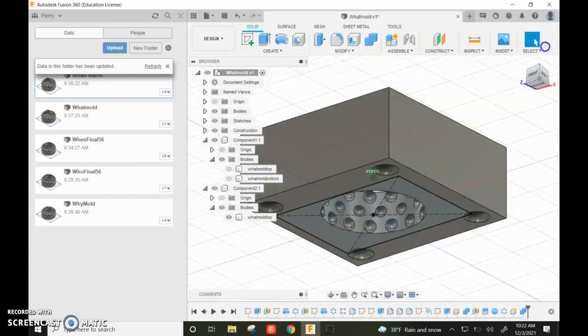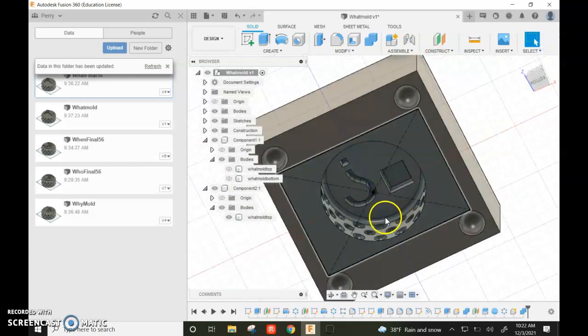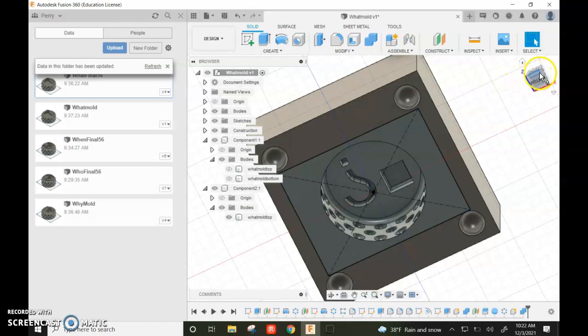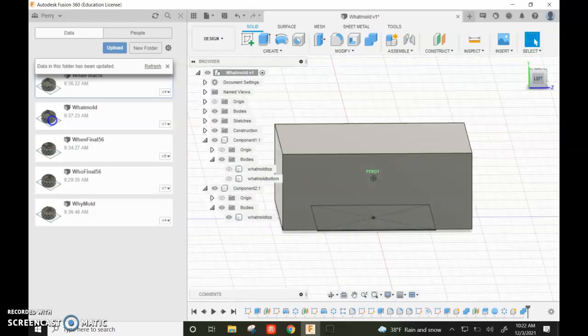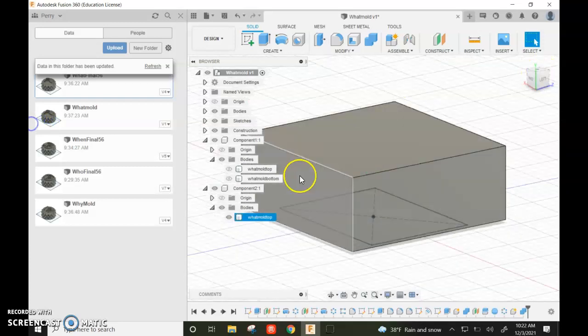Now, if I were to mold like this in 2 parts, I'd have a heck of a time extracting the rubber from this top. Once I pull the molds apart, the fact that these dimpled spheres on the outside of this are on both sides, I would really have a lot of trouble getting out of there. So I'm actually going to split now the top also. So I have that going.